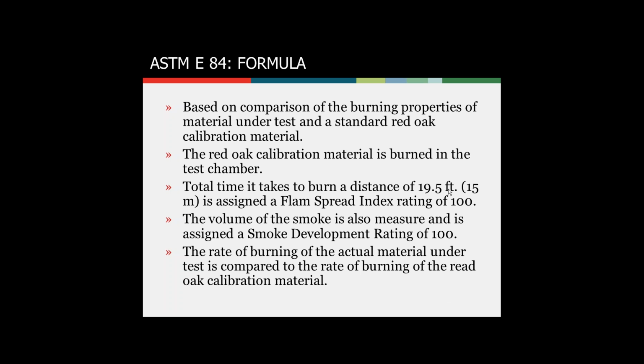The rationale of the ASTM E84 test was to burn a red oak material, which arbitrarily gives a flame spread value of 100, and it arbitrarily gives you a smoke development rating of 100. You then burn real materials, and you compare the burning rates and the smoke rate versus the red oak, and this gives you your smoke density values.